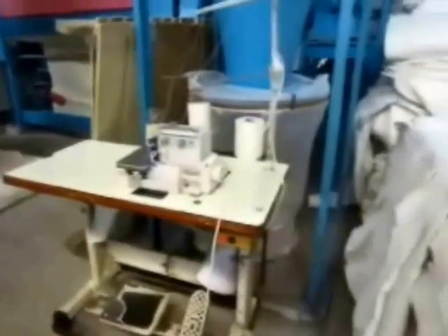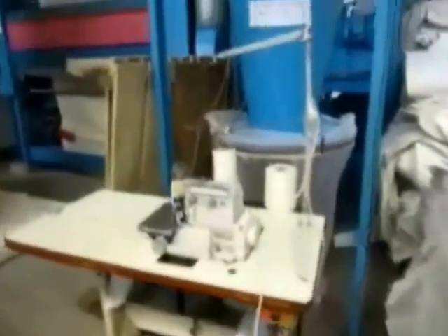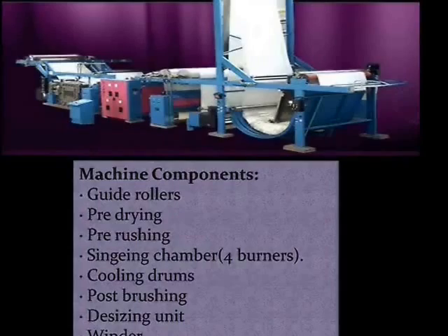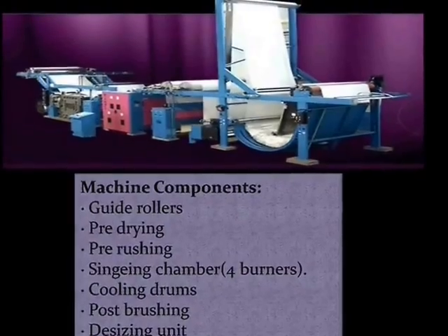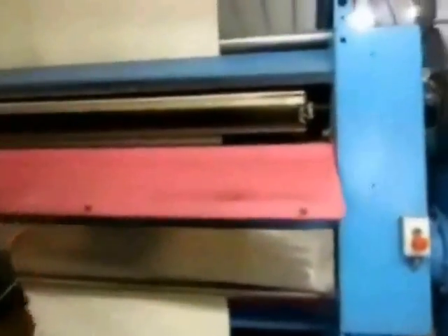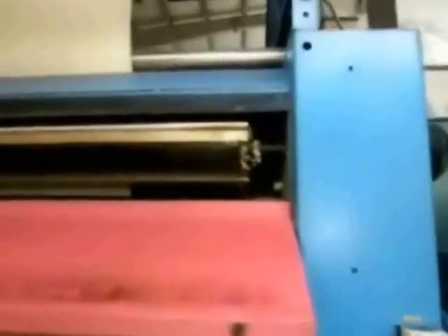Gray fabrics are generally kept before the singeing machine. There is a sewing machine just before the singeing machine where one end of gray fabric is sewed with another end of upcoming gray fabric. At first, the gray fabric passes through the brushing unit. Protruding fibers removed from here are taken away by the air duct suction unit.